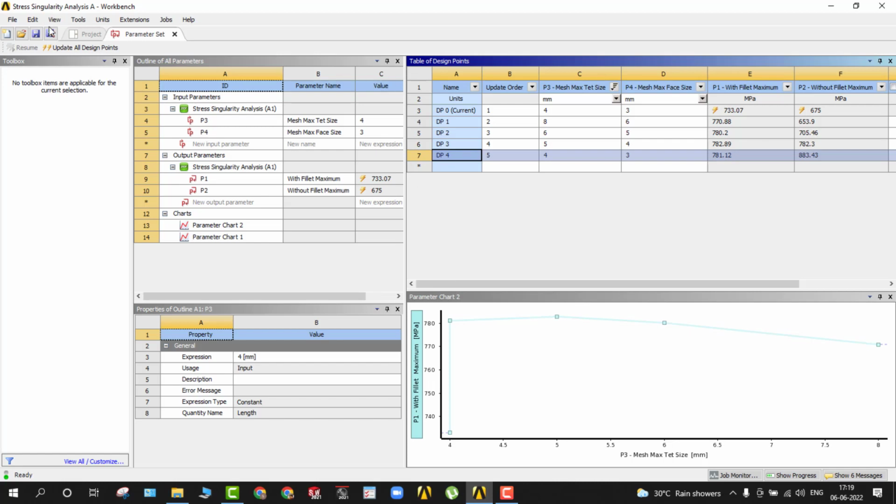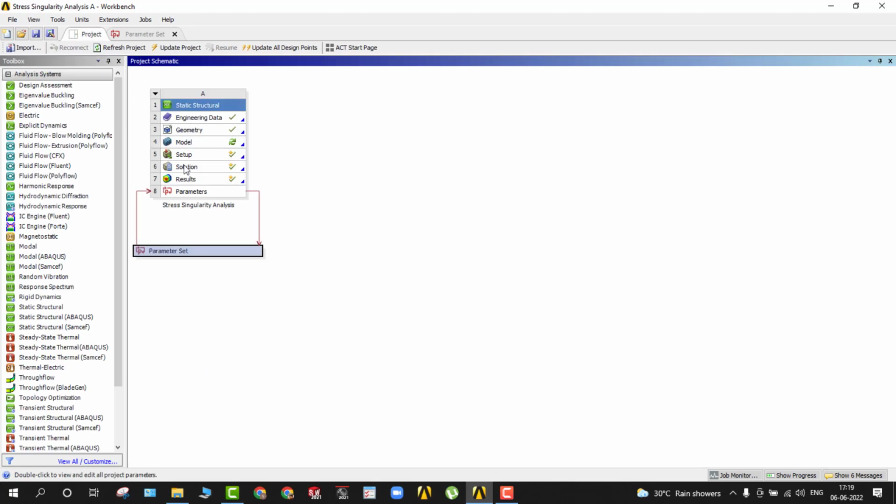Okay, so I have done the same here. So you can update this, or else you can save this entire study with respect to all the parametric studies you have created, dp0 to dp4 or dp5. Then you can just separately open those projects. That is one way to deal with this. Okay, so once you are done with this updating, you can just simply review the results here.